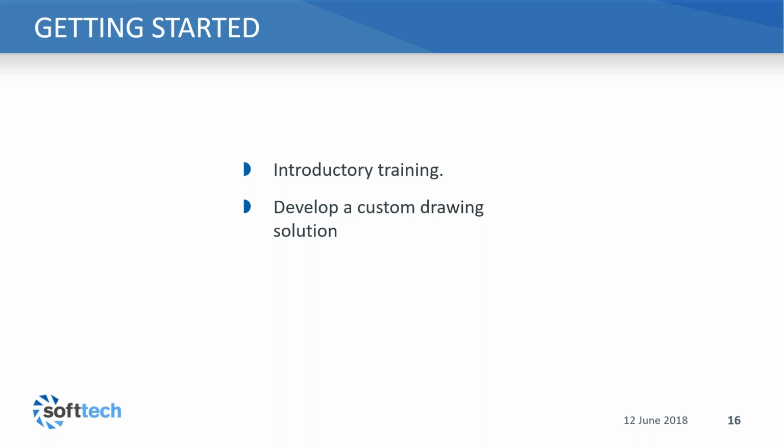Okay, can you show fab cuts and fabrication drawings? If you can determine what they are and you have those drawings in a library somewhere, then there's no reason why those drawings could not be pulled in and loaded up as a block inside the drawing. So there are two ways you could accomplish that. You could interrogate the model, determine where your reference points are, what milling preps you've actually got on those parts, and pull in the appropriate drawing from a library that you have stored on your machine or on your network somewhere.